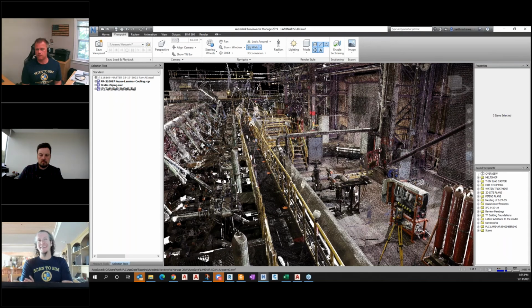That being said, in-place families are generally considered extremely bad practice by any design firm working in Revit. They will kill you if you send them a model with hundreds of in-place families because it bloats the file size massively. And in general, mesh performance in Revit, if you have hundreds of instances of mesh scattered through the family editor, you get some really undesirable behavior, just in terms of performance and stability. So possible, yes. Recommended, definitely not. Just because you can do something doesn't mean you should.